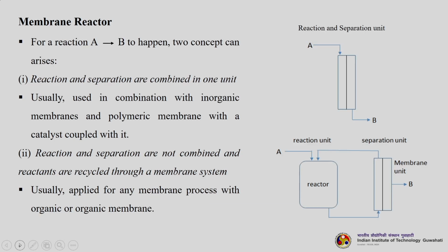So, for the reaction of A and B to happen, two concepts can arise. Either reaction and separation can be combined in one unit, where it is usually used in combination with inorganic membranes and polymeric membranes with a catalyst coupled with it, or otherwise reaction and separation are not combined and the reactants are recycled through a membrane system. Here it is usually applied for any membrane process with organic or inorganic membrane.